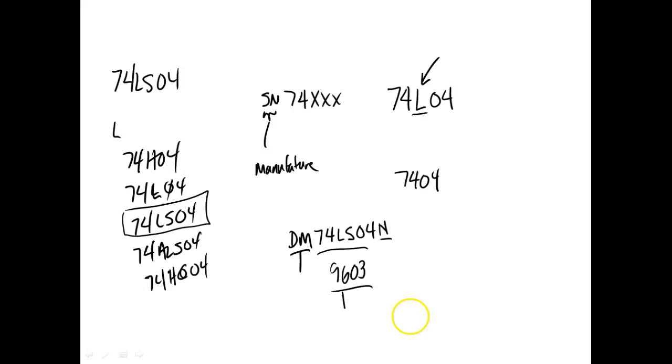So it took care of this guy. This guy's not around much anymore, and the L series is not around much anymore. So just about all our ICs will be an LS. But we're going to deal with some HCs, and we'll learn what this means before long. When we get into lab 2, we're going to hook this up and see what this guy sees as a high and what this guy sees as a high, and they're not going to be the same, but it's still going to be the legal level.